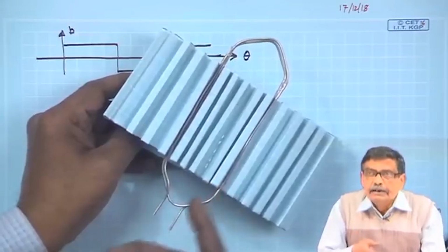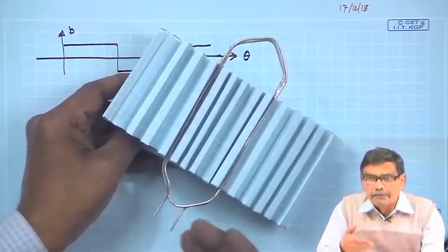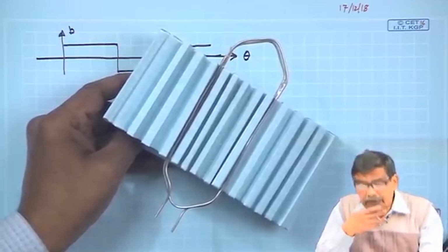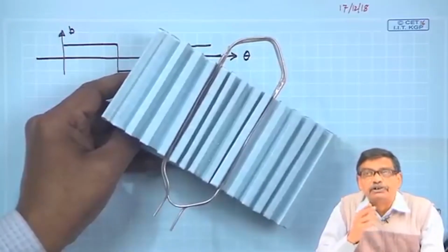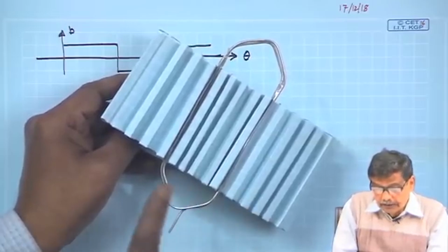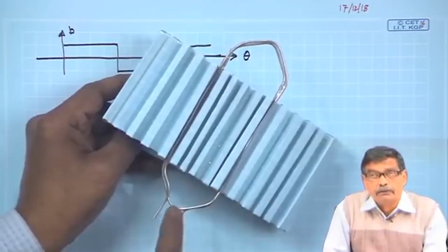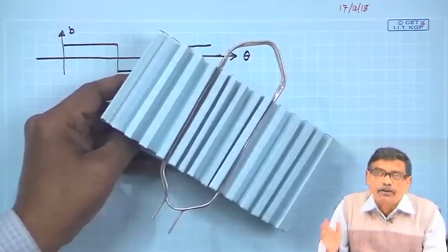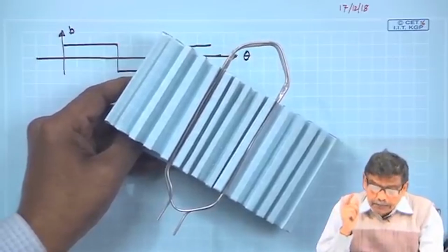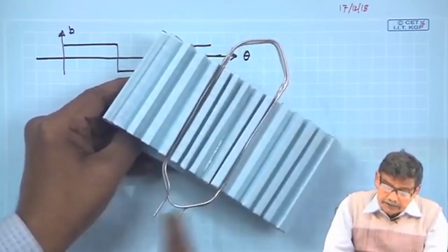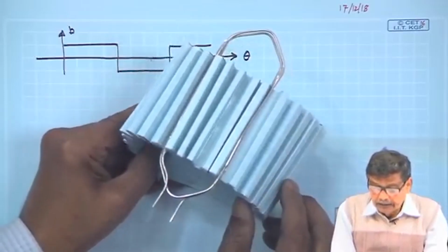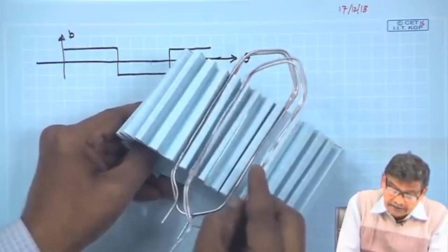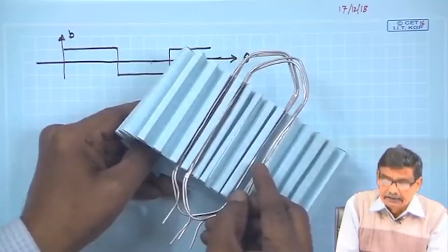Now, this B, if its magnitude is varying in space, in whichever way it varies, the induced voltage will be of the same shape. If it is rectangular, this voltage too will be rectangular. If the B distribution is sinusoidal, the voltage will also be sinusoidal. Another point I want to make regarding this arrangement is that this is how different coils will be placed in their designated slots.